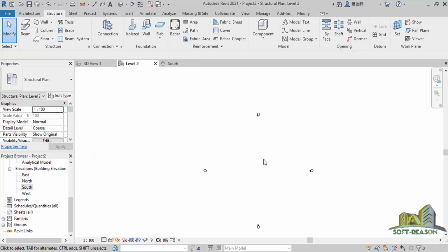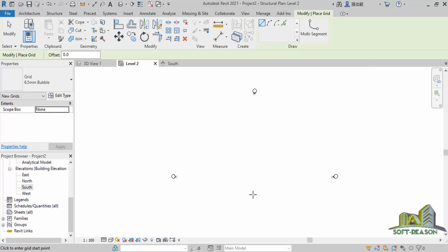And then the next thing I will do, I will enable fine. So I will go to this particular ribbon. If you check, you will see the structural, the connections, and other tools. So what I want to do is form a grid. So I will click on grid, or you just type G R. So I will be having one grid, just like this.